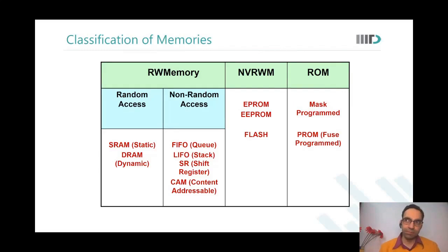Programmable ROM means, for example, let us say there is some part of the system which is failing. You want to disable it, or you want to send a little higher voltage to it so that it starts to work. Now, since this part is already failing, or you suspect that it would fail in the field, you already calibrate the system in such a way that this chip would generate a higher voltage than regular. These PROMs are fuse-based, and they are typically used for calibrating the system so that it operates at an optimum, say, voltage or frequency or throughput.